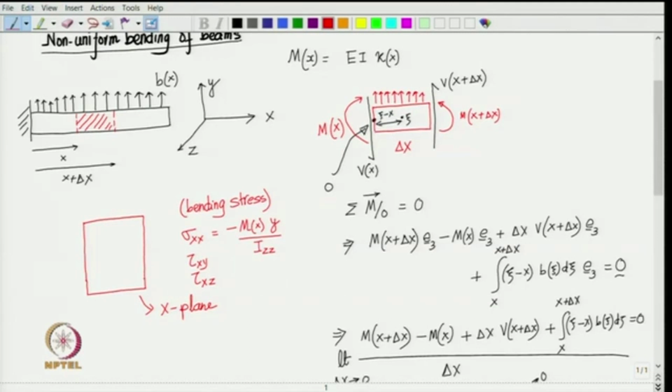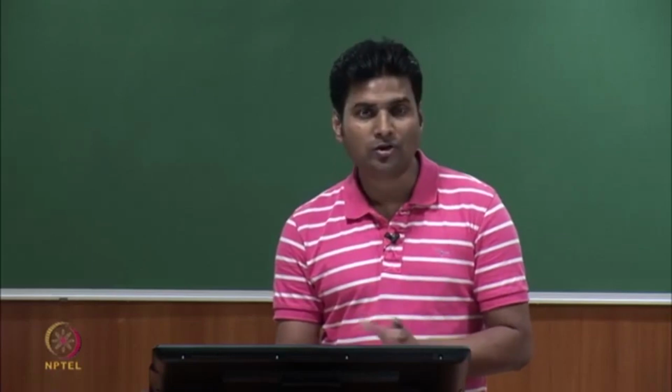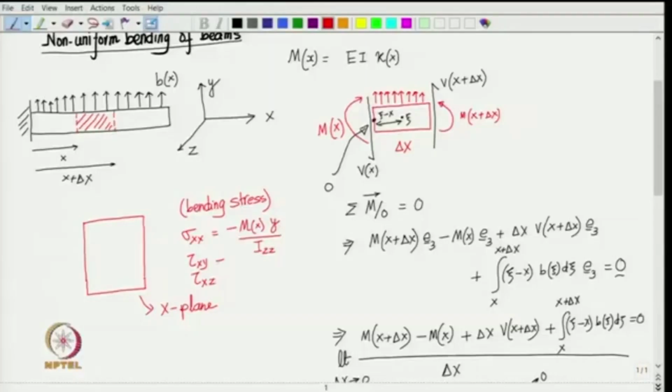This is the component of traction in the y direction, right. You see, we have used the symmetry that tau xy is equal to tau yx. So, we are talking about traction components on the x plane and then in the y direction. So, that is tau xy. If it was not symmetric, then we would call it tau yx. Anyway, so tau xy also cannot be equal to 0.